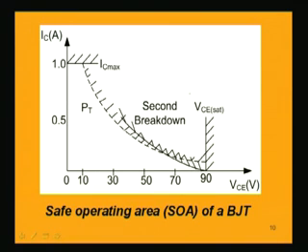So, here we are showing the safe operating area. This plot has the maximum collector current given by IC max. This is just an example having these values, it is not always that it has only these values, but we are considering a typical case for an example. And the sustaining voltage is given by this upper bound on the collector to emitter voltage.